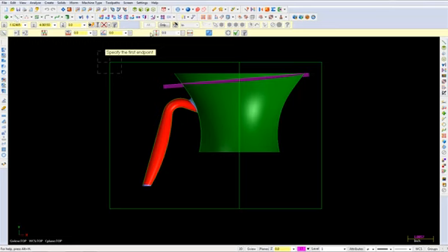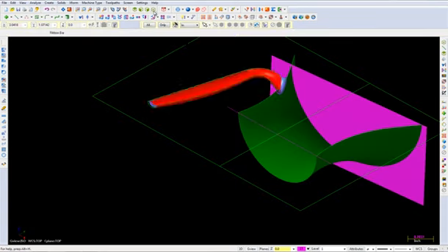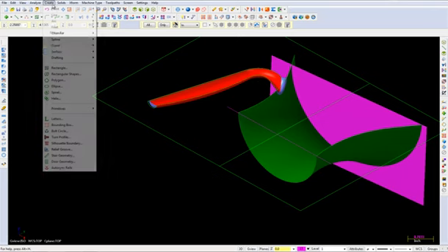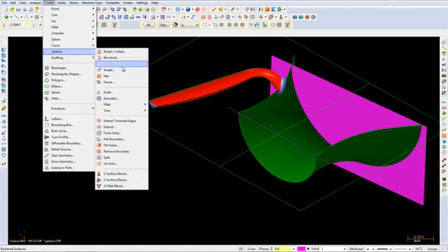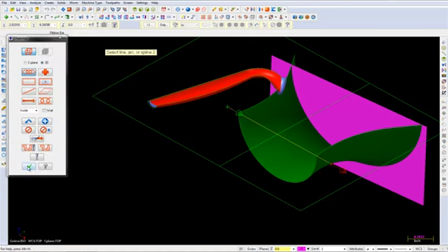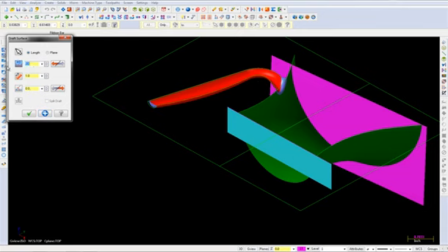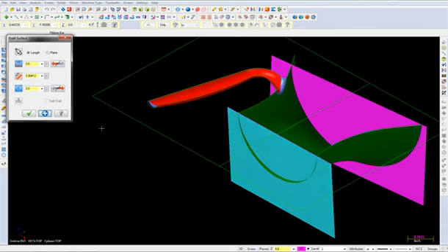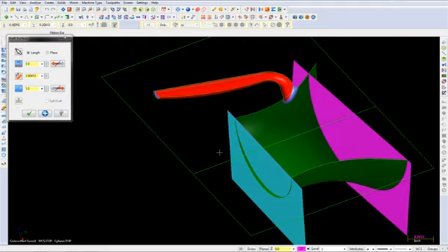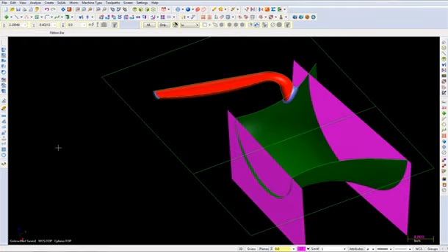Choose the command Create Line Endpoint and enable Horizontal in the ribbon bar. Sketch a line from here to here. Enter the Y value as -4 and press Enter. Select the OK button to exit the command and return back to the isometric view. And draft this line the same way that we did as previously shown. The result should appear as shown. Choose the OK button.